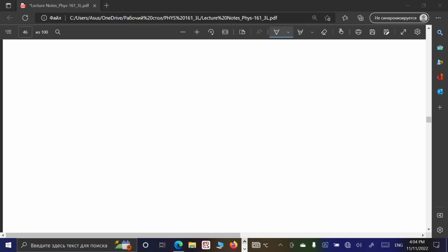So we clearly define two regions in the refrigerator where we have low pressure and high pressure. And what is the driving force for this work done on the system in order to make the heat pump working? The compressor.